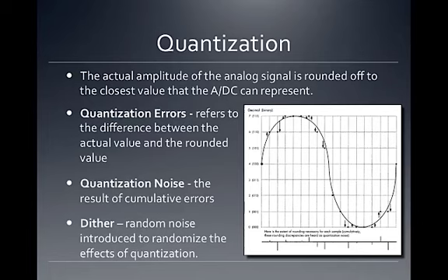quantization errors are very random noise. And if we mask that random noise with more consistent noise, again, these oxymoron type of terms I'm using, consistent noise would be like white noise or pink noise, it's a little bit more pleasing to our ears when moving from 24-bit to 16-bit. And we're talking really, really soft noise that sometimes you wouldn't even know is there.